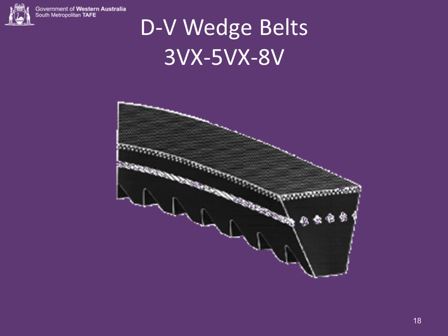DV wedge belts are oil resistant and static conducting. They permit compact, lighter weight drives. High strength tension members deliver maximum power with minimum stretch. They're built for long-term dimensional stability. Molded cog construction under 5 meters, 5,000 millimeters in belt length.